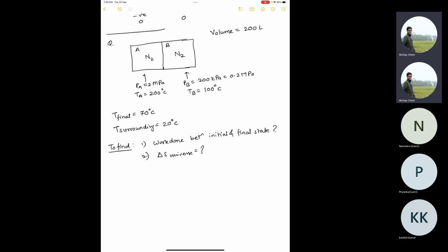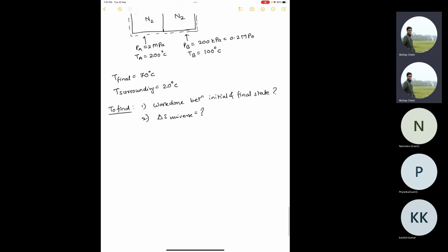Actually, for such type of problem, wherever you get this rigid container type of problem, my personal advice is to take this whole rigid container as your system, because then you don't need to worry about what is happening inside. Your boundary is covering the rigid container, right? And normally there is no movement, so your boundary work is 0. So therefore, the first question itself becomes 0.